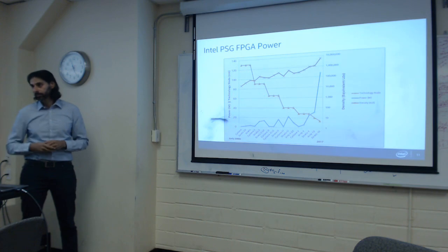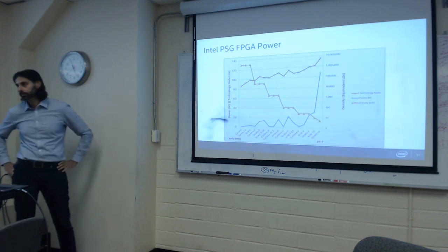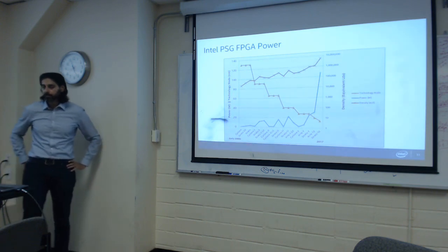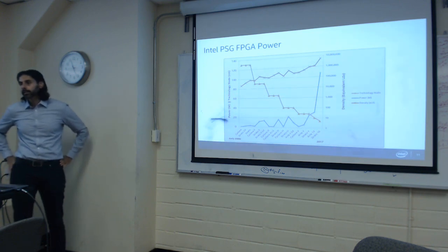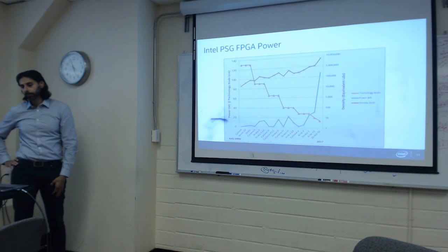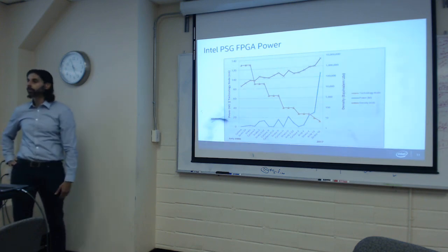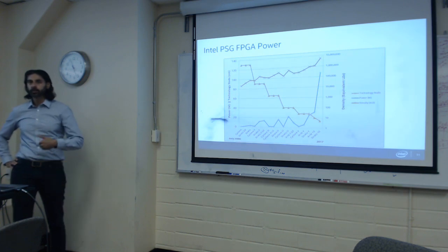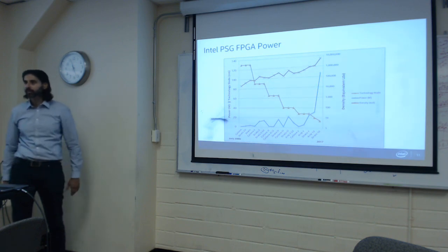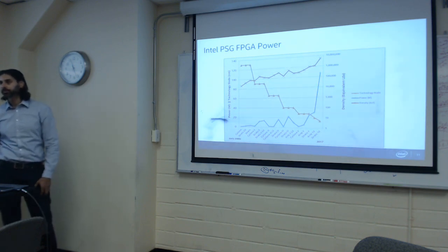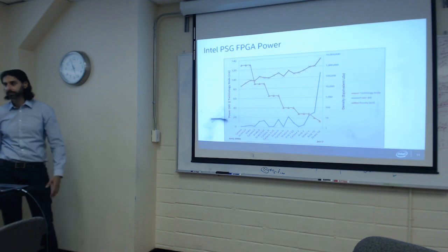Good. I guess a question on, so is this the largest FPGA, fairly full, running at a reasonably high clock frequency? Like how do you generate the numbers? So, taking each of these FPGAs, 80% full, running at the target frequencies that we expect customers to use in that application. So again, it's an assumption. So a typical clock frequency the customer achieves, 80% full, is like the largest device in each generation. Yes.